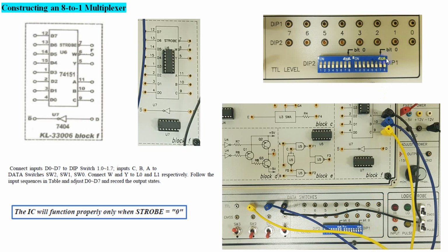So if I need to give input to something connected here, I need to use this one. Don't consider the numbers down below, forget about them, just consider this is bit 0, the next one is 1, then 2, 3, 4, 5, 6, and 7 accordingly. So wherever you connect your input, for example, if I connect from here and from here, then you need to give 0 and 1 from these two here.